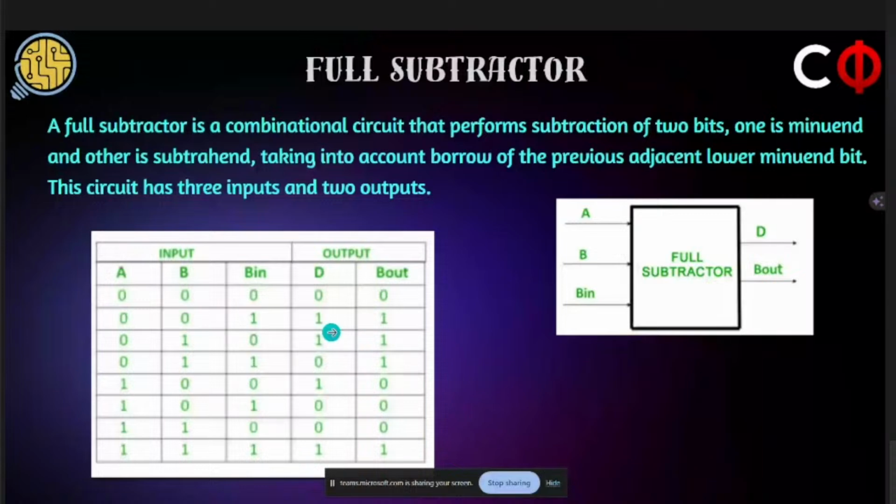Now, let's go with the fourth example. A is 0, B is 1, B input is 1. B input is nothing but borrow input. It's the same reason, just like how we named the third input in full adder as carry input, we name the third input in full subtractor as borrow input. Why? Because a very similar procedure as in a binary adder can be seen in a binary subtractor as well. The borrow input will be moving on to the consecutive full subtractors. So that's why we call this borrow input.